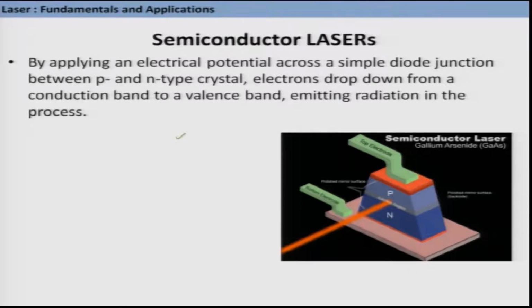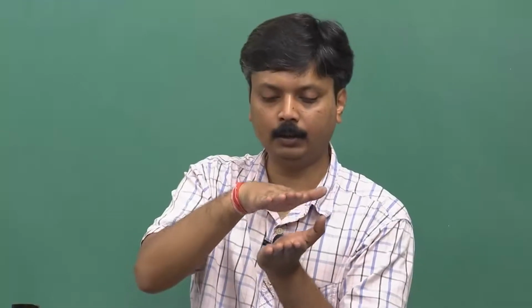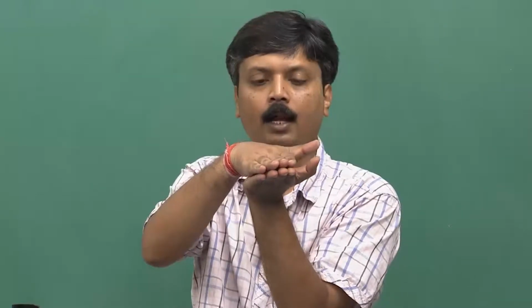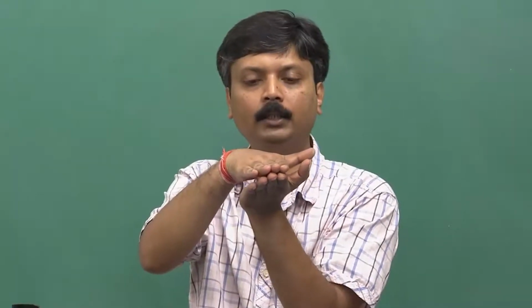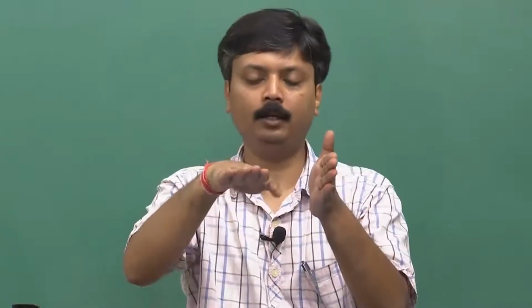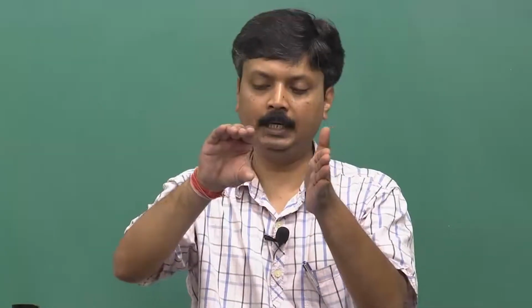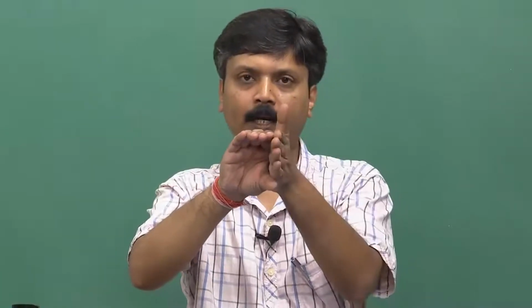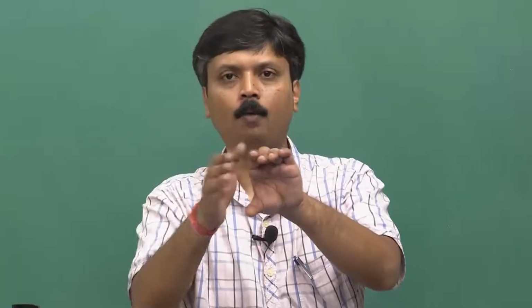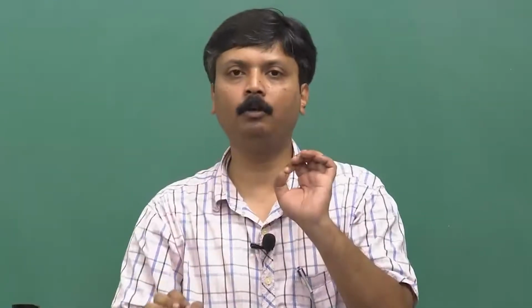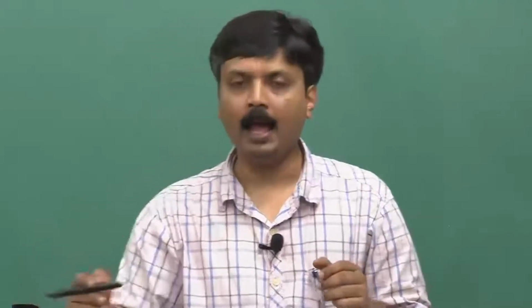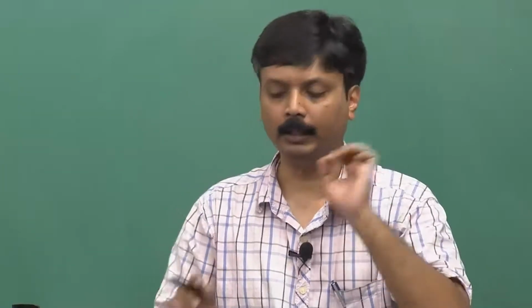So essentially what I have is a p type crystal and an n type crystal, placed like this. Now I bring two mirrors. This is the mirror surface and this is my p-n system, and I put this mirror like this and bring another mirror from this side and put it here. One of these will be highly reflective, another will be partially transmittive, as always, and from the partially transmittive mirror I can get the laser output when I give the adequate voltage to my system.